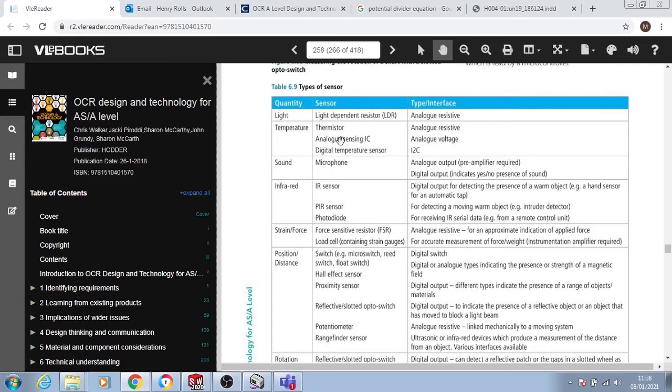So yeah, all sorts of things. By the way, there is quite a good little analogy. It's quite handy to remember which way round these two work, because these are the most common types of sensors you'll see. So light and temperature. My weird little analogy that makes me remember which way round they go is think of chocolate. On a hot sunny day, chocolate melts, and when chocolate melts it flows. So think of chocolate as being like that variable resistor, the thermistor. When it gets hot or when it gets bright, the current flows, so the resistance has dropped. So basically when these sense light, the resistance lowers. Just an easy way of getting it round.